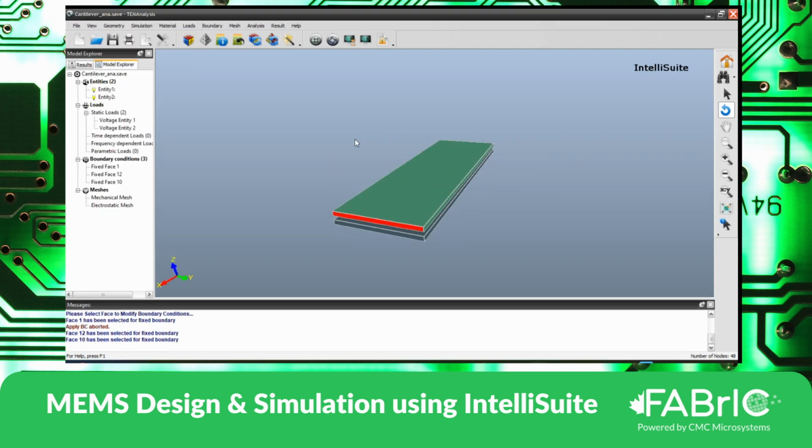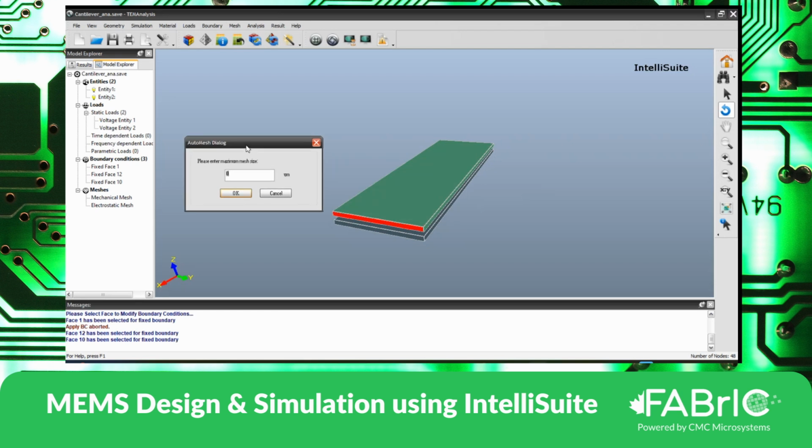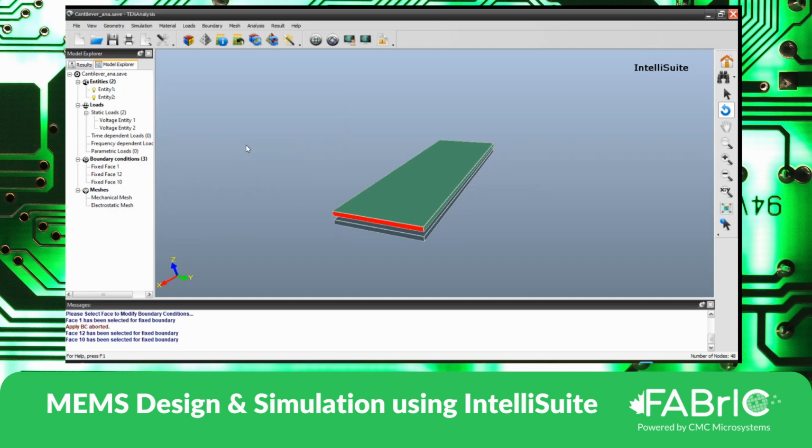Okay. So now we are done with boundary condition. We are going to mesh. Now mesh is a tricky thing because high refinement in mesh always gives better accuracy, but we have to compromise on simulation time. So now what I would say is this is a 300 micrometer by 100 micrometer geometry. Mesh it to 30 micrometers.